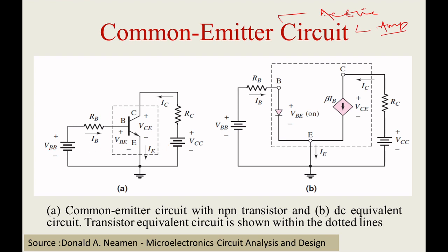It is an external DC supply connected to the transistor to drive the circuit. Here VBB is connected to the base, so just to remember, I kept VBB. VCC is connected to the collector. This is just for my understanding, it's not mandatory. RB is a biasing resistor connected to the base terminal, and similarly RC is connected to the collector, it is a load.